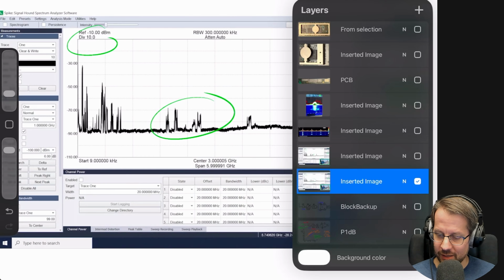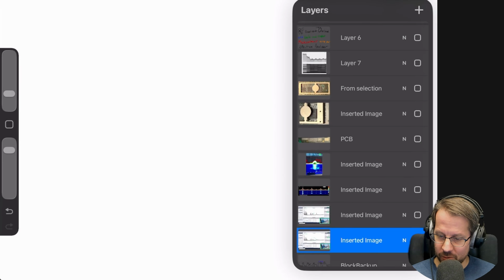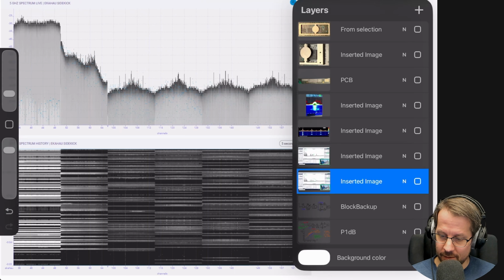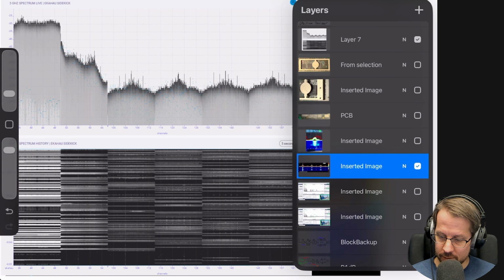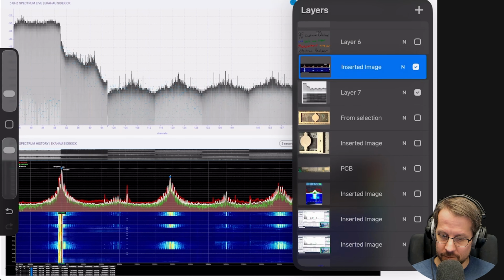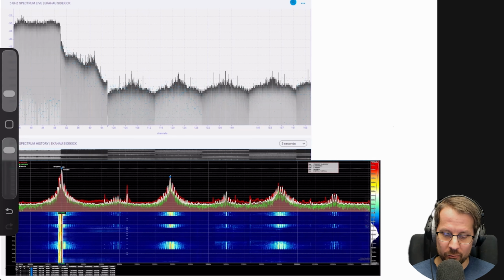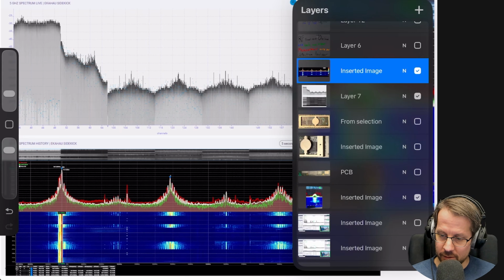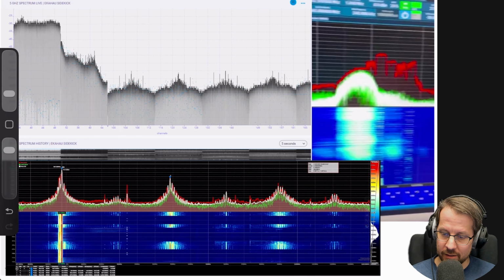I also have some other quick examples here that I can show. This is a really complete overload of the complete ADC. I have some other examples here. Here are some intermodulated products from a really strong transmitter. So you see the copies of that signal. It's multiple signals that have been copied. And here is the same little lump that you get in this right picture that you got in the other spectrum analyzer, right? Because the ADC or something got overloaded.